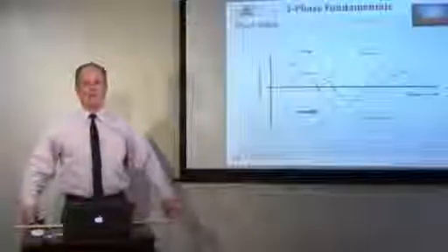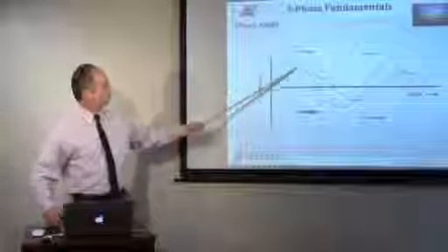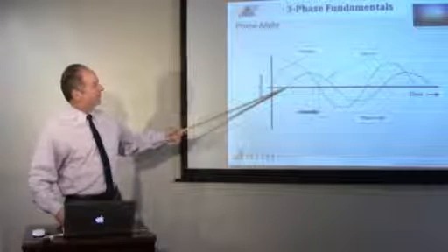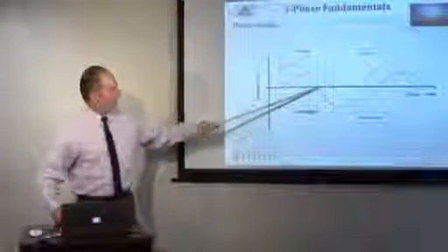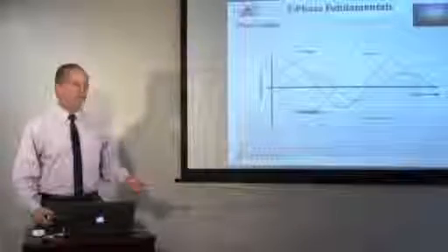But I want to talk to you about the relationship between voltage and current in these as it applies to three-phase power systems. First of all, we have resistance, inductance, and capacitance, all running with AC sources. Now, here's the phase angle we talked about earlier. You have a voltage, which is your reference. Remember, we like to choose voltage as reference because that's where our generation starts, with the generator. And our current is lagging, which is indicative of an inductive load. And there's a phase angle between the voltage and the current.